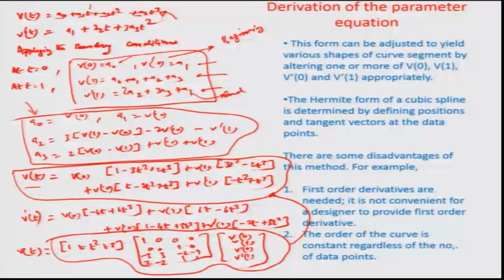So, computationally what we can do is to let off all these different end conditions in terms of the coordinate values and the slopes, and vary the t between limits 0 and 1, or maybe a local t which varies between some value to some value, a t min and a t maximum. Maybe it can be 1/3 and 2/3, or it can be half and 0.67, something like that, and be able to plot on a local basis the section of the curve that we would like to have in this particular case.